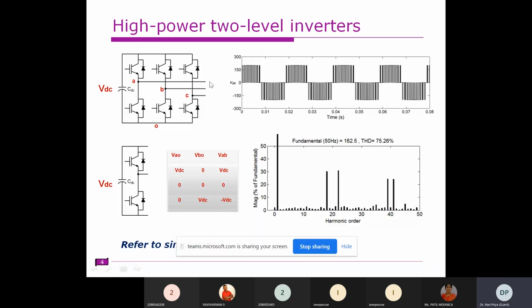Right, those converters are called line commutated converters. They have an issue with respect to obtaining the output voltage, because the thyristor devices, which are nothing but line commutated devices by design, have a limitation in obtaining the output voltage and operating frequency also. So what they try to do is replace each thyristor device with an IGBT, and the advantage of this IGBT is that it is a self-commutating device. Not only IGBT, you can use MOSFET also, but they are self-commutating devices.